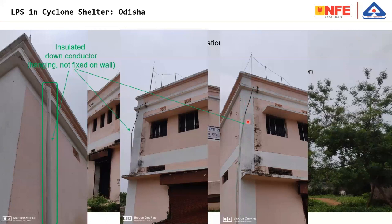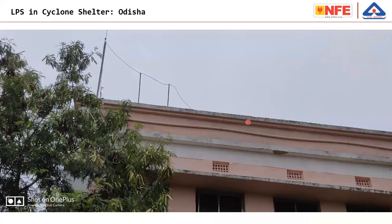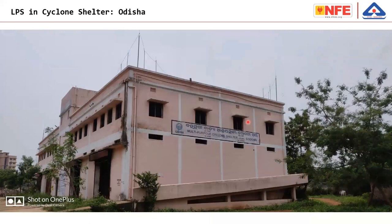Now, protecting people inside this shelter. This shelter is an RCC building. It's a properly constructed RCC building. You don't need to have lightning protection for this building to protect people. If you want to protect the structure, you need to have a lightning protection system. If you want to protect people, simply ask the people to go inside the building, let them sit inside the building, not go near windows, and not touch electrical items. That is the safest way.